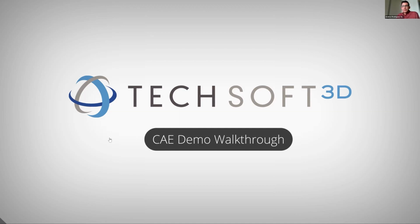Now let's go for this demo. Our consulting engineer Toshi in Japan took a few days to create this browser-based application to showcase what I just presented, the full coverage of the workflow. We'll be importing a bracket's design, adapting the geometry for the simulation needs with Parasolid. Actually, I didn't talk about Parasolid, but David did earlier on. We're going to edit the geometry, then we will mesh it and perform a static analysis to determine which of fillet welding or groove welding is the best way to manufacture the part. So I'm going to run the video.